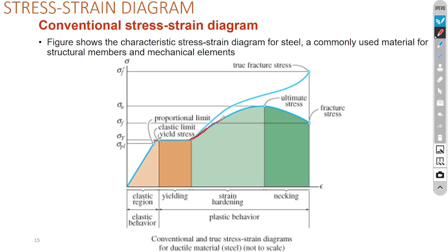Atomic bonding forces per unit of area increase. But there is a limit. Increase, increase, increase, and then reach this limiting value. If this limit is exceeded, atomic bonding forces won't be sufficient to balance the externally applied ones. In a uniaxial test, the cross section will be drastically smaller, and then atomic bonding forces thereafter cannot balance the external loading and the object is broken, fracture occurs.